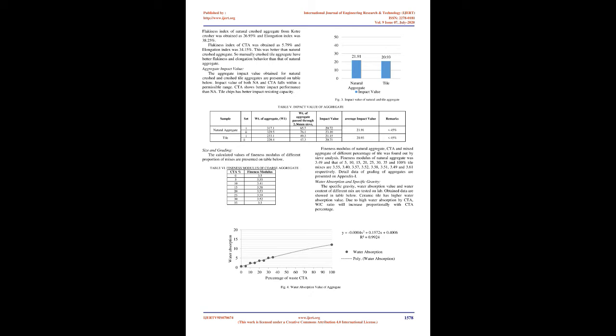Fineness of cement is determined by following guidelines outlined in IS 4031 Part 3. Setting time. Initial and final setting time of cement was determined following the guidelines outlined in IS 4031 Part V. In our cement sample we found 55 minutes for initial setting time and 325 minutes for final setting time. This is in between 30 minutes and 600 minutes.